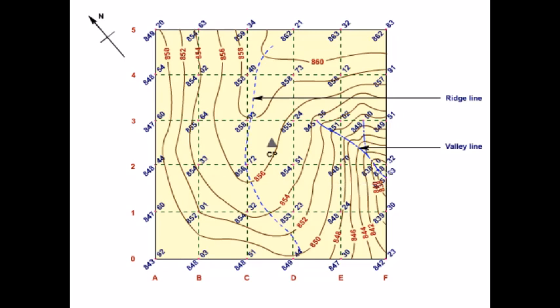This line is probably showing a stream or a river or something, but usually you don't have these on the map, so you just have this distinct shape over here, and these shapes that successive contours are making. So this line, like we discussed before, represents a valley line.